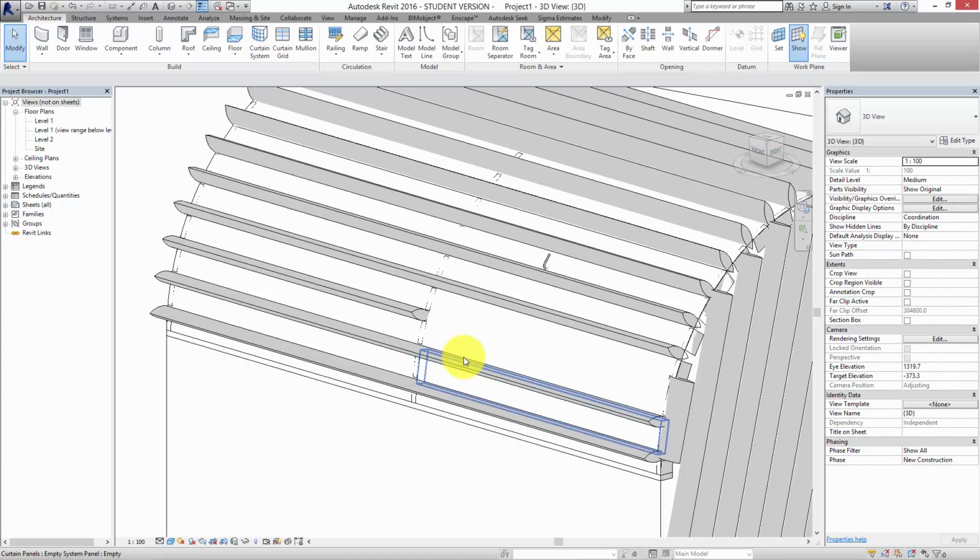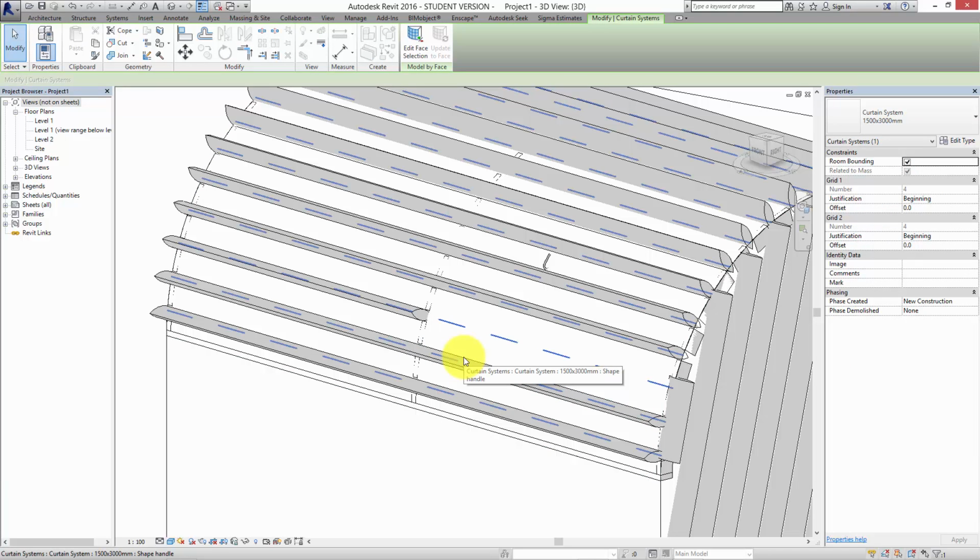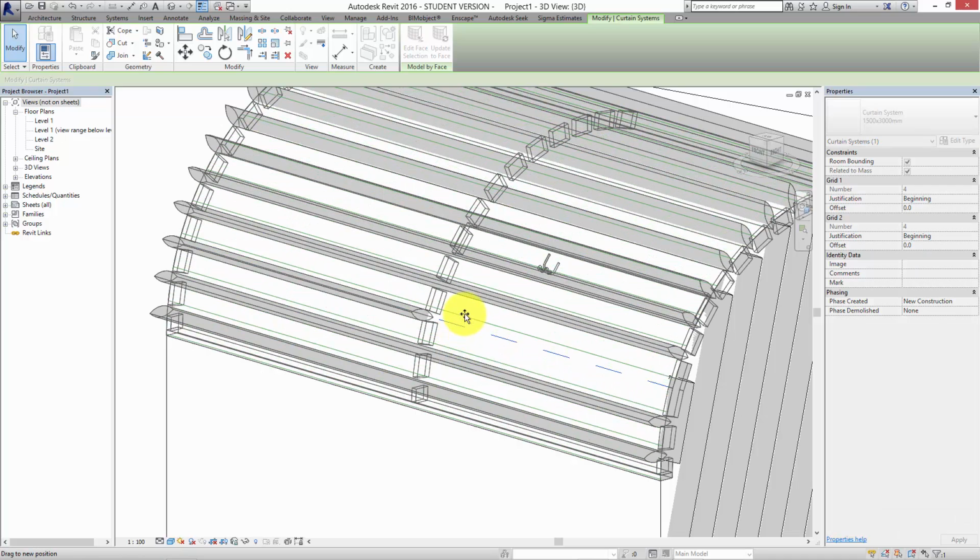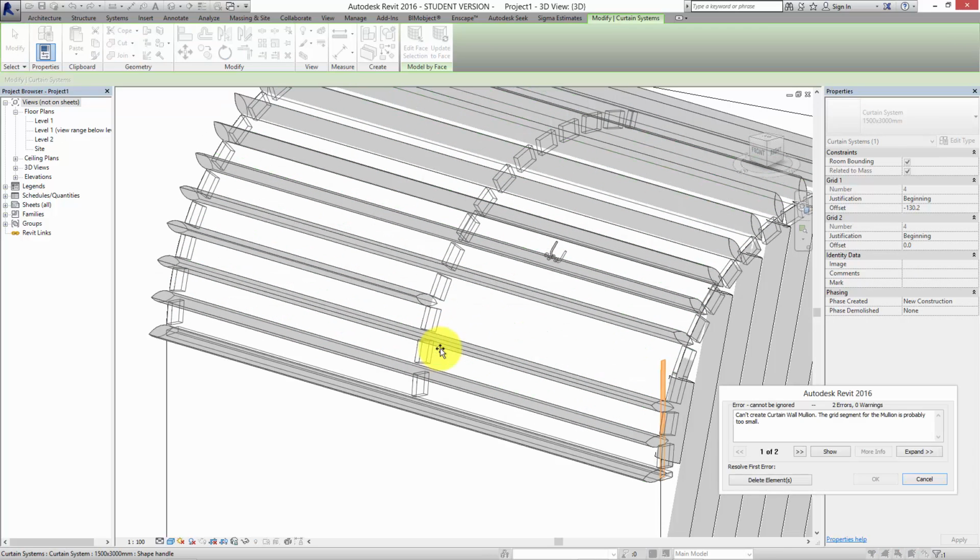Yeah, this one. No, yeah. There's one. Yeah. Just one is not possible. Doesn't seem to be possible. No, you need to delete the element. So what I would say is you would make your curtain wall so that the modules between them line up in some kind of way. So if you wanted to have gaps or different things going on, that you need to set it up that way. Two different categories. Yeah. Yeah, something like that.